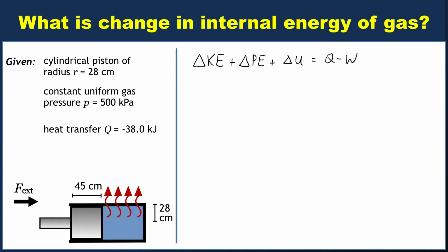Well, as always, conservation of energy is that the change in total energy is Q minus W. Now, in this case, we can't set Q and W equal to 0 for obvious reasons. We have both heat transfer and work. We can actually set the kinetic and potential energy changes to be 0, though. In the case of the kinetic energy, the idea is that we moved the piston slowly enough that it didn't introduce large bulk flows into our system. Likewise, even if things moved around a little bit, it would be similar to turning off a ceiling fan and then watching what happens to the air in the room. It's not as though the air keeps circulating for an hour after you turn off the fan. Wait just a little while and that kinetic energy will be dissipated into internal energy.